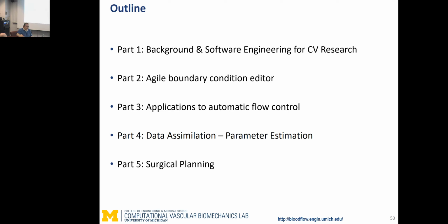So it's parameterization. That means that you have to iteratively refine your simulations, both the mesh and also the values of the parameters of your model. It can be elasticity values of the vessels. It can be your heart model parameters. It can be your distal circulation parameters, until you match the clinical data. Each of these iterations implies basically running a full problem, which is, of course, expensive. But the expensive part is the fact that you have to do it over and over again. And what's frustrating about it is that it's, for the most part, a very ad hoc, non-systematic task.